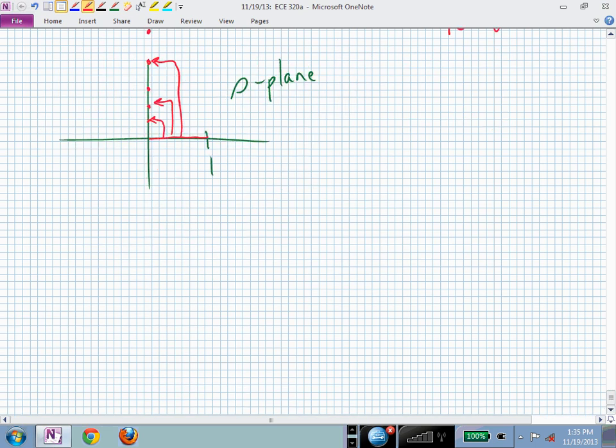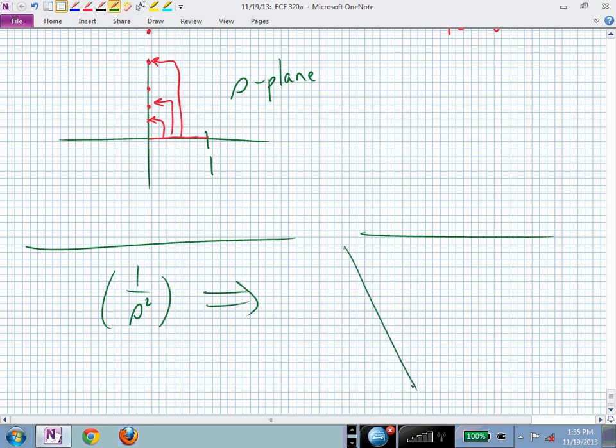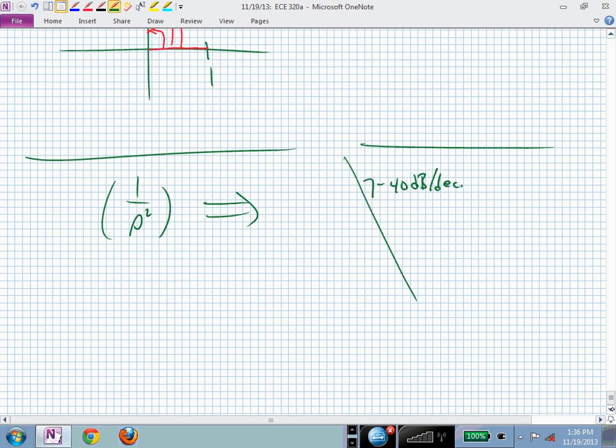So now the question was, if we have two poles at the origin, if you now had 1 over s squared, now your magnitude factor is going to be doing this, isn't it? It's going to cross the same 0 dB at 1, but now its slope is minus 40 dB per decade. And it keeps increasing at that slope. Is that okay?